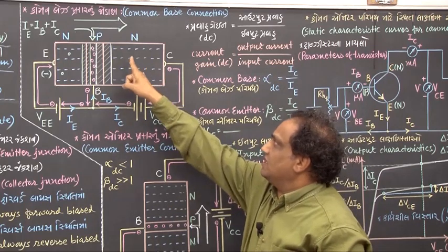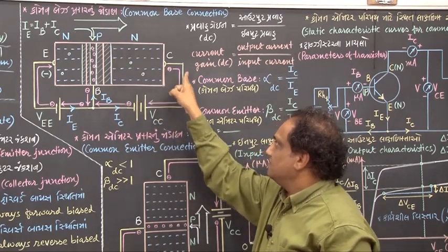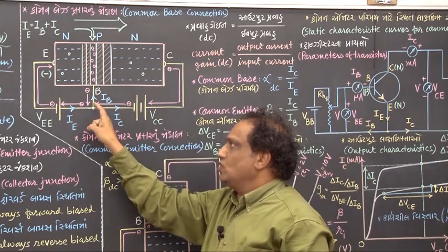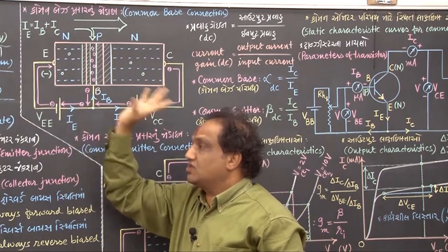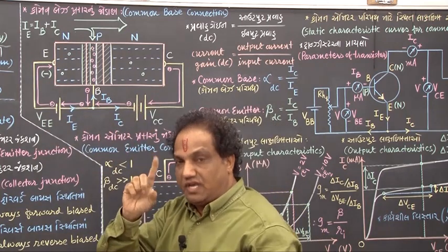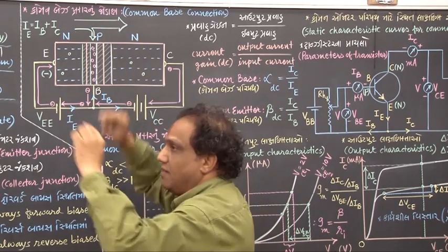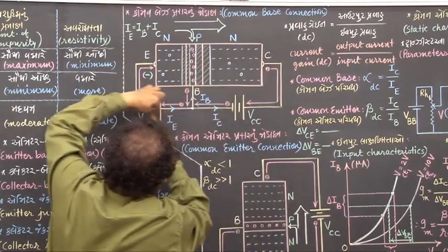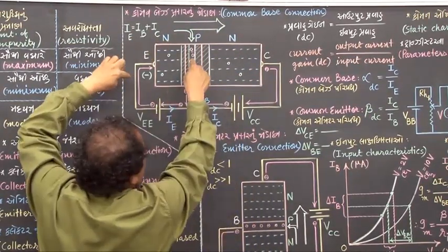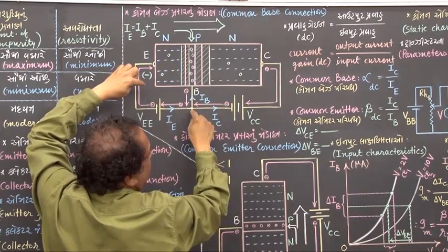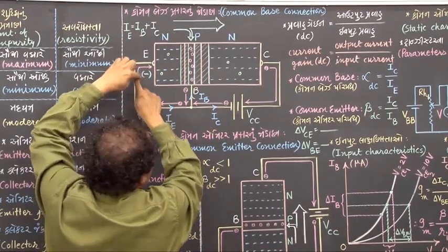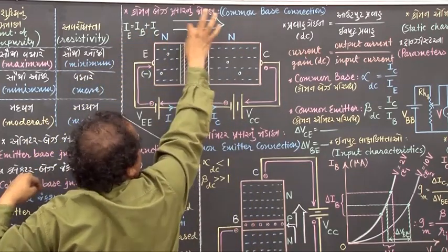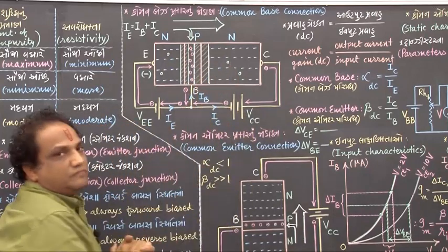Now, in the collector, these electrons are repelled this way. Look. Fine. And both these electronic currents combine here to give you the total electronic current flowing in this direction. Correct? I am showing you how the electronic currents are getting dissociated, I mean, how they are getting divided. Look, this way. Correct? This is the junction from which they depart, and this is the junction at which they associate. This way. Fine. So here it is 100%, here is 5%, here is 95%. Got it? Fine.